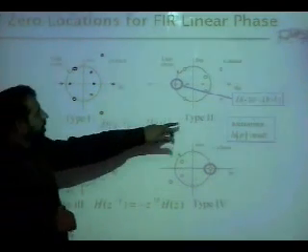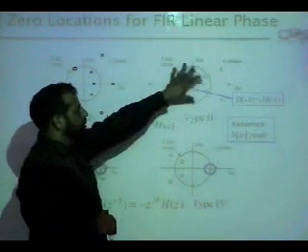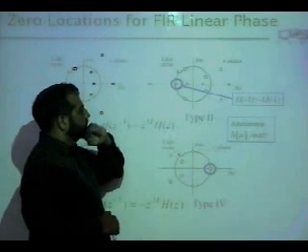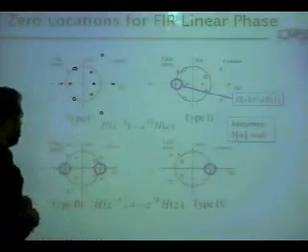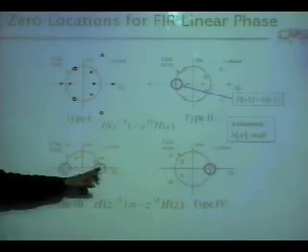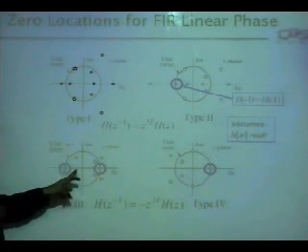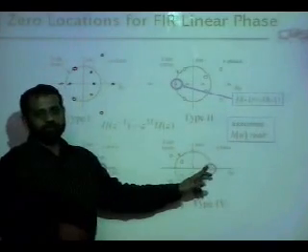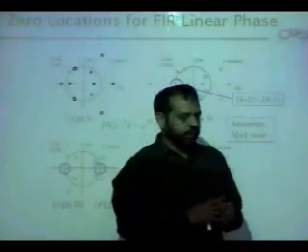So you can easily plot this. For type 2 filter, this is true. There has to be a 0 here. Otherwise, you know what, assuming Hn is real, which we always assume. Type 3 filter, no low pass, no high pass, because a 0 here, a 0 here. Type 4 filter, no low pass, because a 0 here.